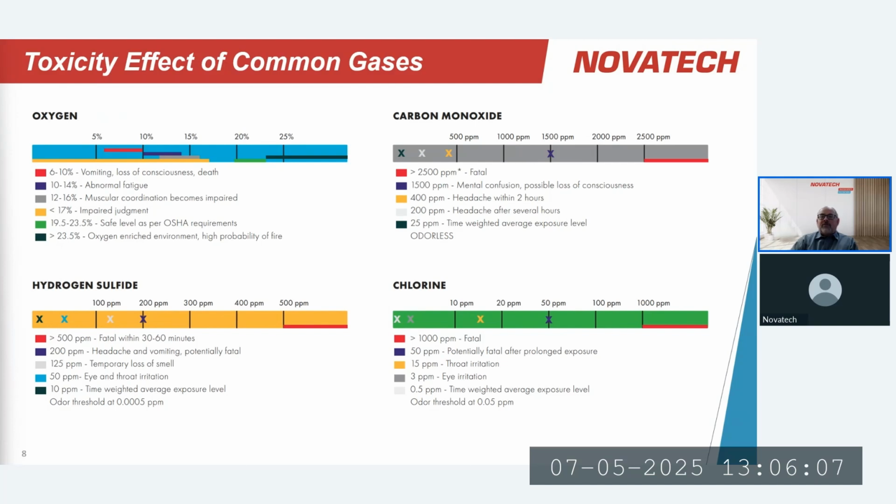When we're talking about hydrogen sulfide, concentrations in the tens to hundreds of parts per million can cause problems. And in fact, beyond 500 parts per million can prove fatal. So these are relatively low concentrations when you think about the fact that when we talk about flammability limits, we're usually talking about percent levels, 3, 4, 5%, maybe even more, depending on the nature of the hydrocarbon. These concentrations of H2S may occur long before we reach flammability limits.